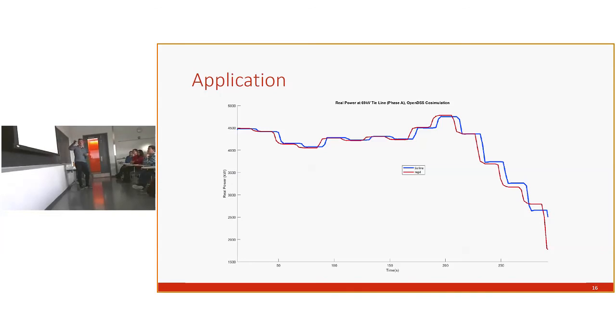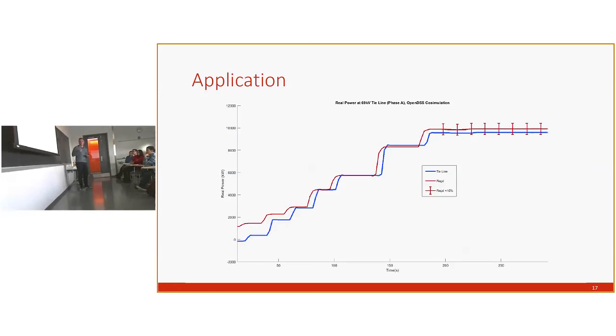Okay. So now we have the first 5 minutes of the Reg D wave. This portion was shown to showcase the downward ramp that you see towards the end of it, where we are still maintaining the 5% between the Reg D and the tie line all the way through. And now we have the second 5 minutes, which is to show a steeper upward curve. The lines over here on the right, or the bars, indicate plus and minus 5%. So because the tie line power exchanged is within those bars on the Reg D line, we are meeting the plus or minus 5% spec.